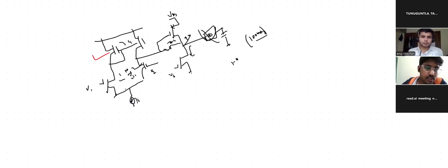For the gm of 3 and 4, we got it, but one more assumption we made was that we assumed a minimum common mode range and maximum common mode range for the inputs. And we found one overdrive value for proper operation of the 3 and 4 MOSFETs, and we got gm3 from that. Okay.